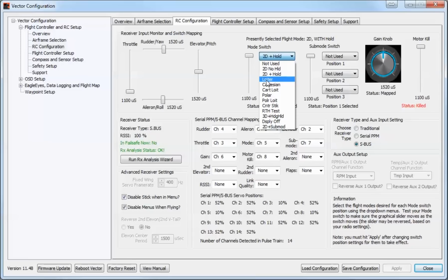The idea is that you can fly it similarly in the way that you can fly in 2D mode, but the point is when you take your fingers off the control surfaces, it will actually stop flying in that position. So it is a very good one for beginners. I'll talk in a moment a little bit about why you shouldn't necessarily take off in loiter mode as a standard. This is on the advice of Eagletree actually, but for the moment anyway, that covers loiter mode. It's really the best mode for GPS fix.